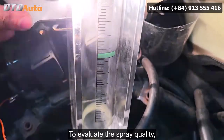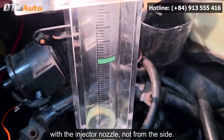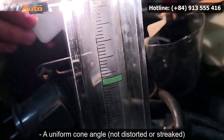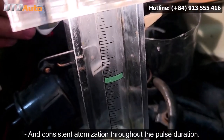To evaluate the spray quality, ensure your line of sight is directly aligned with the injector nozzle, not from the side. A proper injector produces a fine mist-like spray pattern, a uniform cone angle, not distorted or streaked, and consistent atomization throughout the pulse duration.